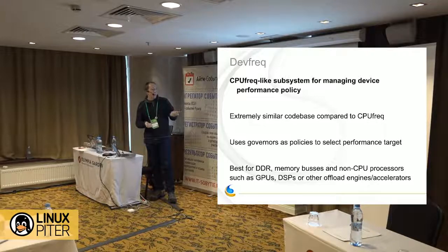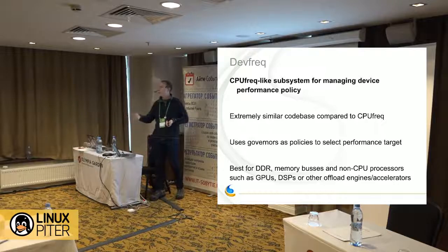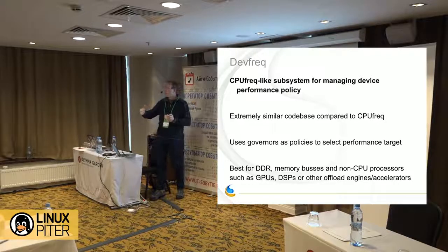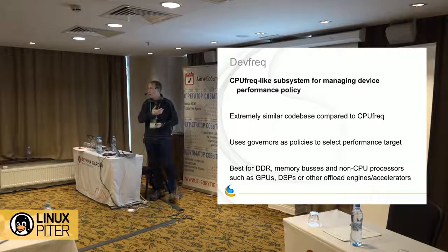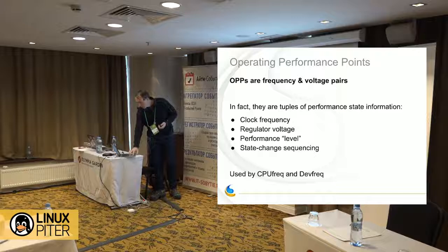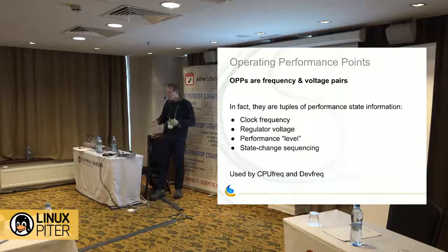You know, if you have performance counters, for instance, for your memory bus, and you can detect that you're over a certain saturation level for your bus, then maybe DevFreq is a good opportunity for you. That's a place where you can receive the interrupt that you get when you hit your saturation limit on the bus and increase performance there, so you're not oversaturated. The OPP library is just a simple data structure for storing tables of common performance information and doing operations on those lists.